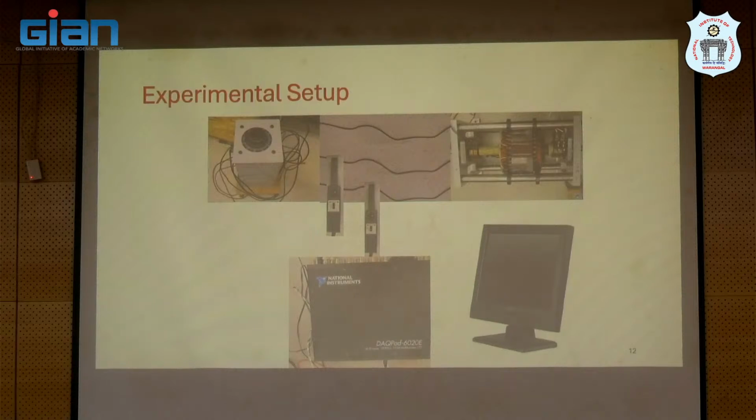Yesterday I was chatting with a couple of you, and oscilloscopes nowadays have storage capability, and most of them are 8-bit. So you have to check whether 8-bit is sufficient or not. But any low-cost microcontroller might be able to get you data acquisition at a reasonable bit, like 12-bit, which is quite common, right? So you should be able to do that. ADC count is quite easy, so you can use that to acquire data. You may not have to invest in expensive equipment as far as data acquisition is concerned. You might already have it, or you might buy low-cost components as well.